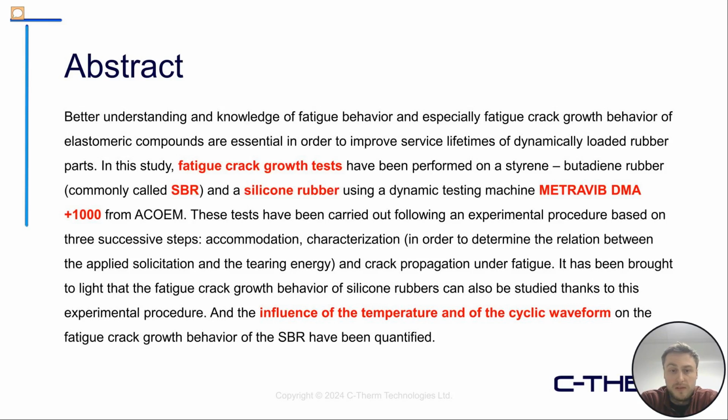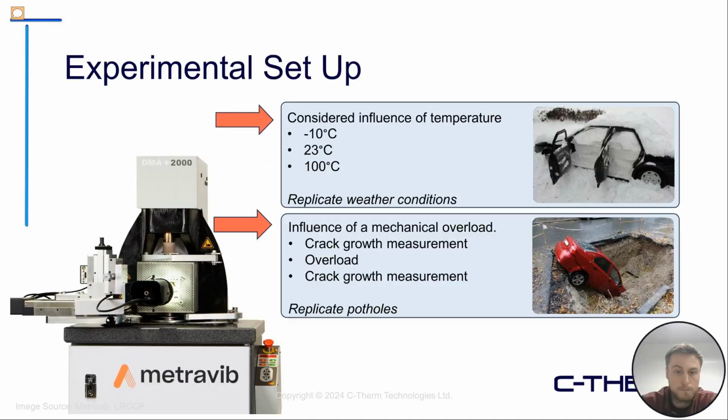The group did fatigue crack growth tests on SBR and silicone rubber using Metravib DMA, and some of the effects they were considering included the influence of temperature and the cyclic waveform on these materials. The two tests I'm going to focus on here are how they considered the influence of temperature. They considered -10, 23, and 100